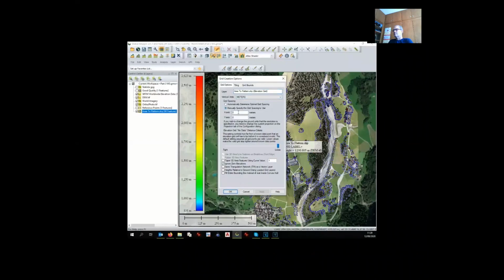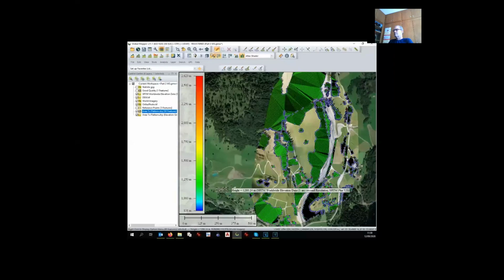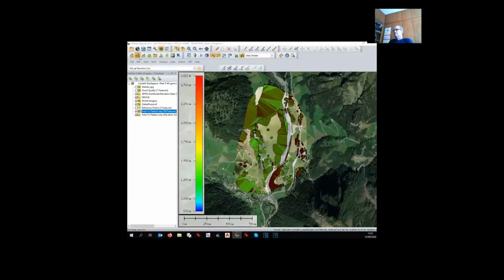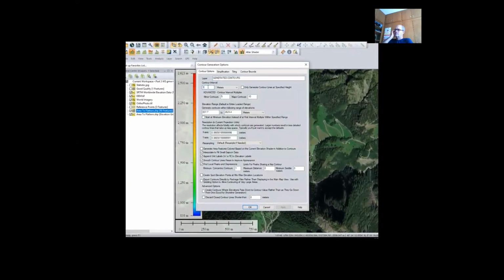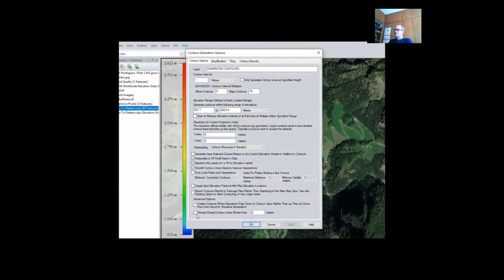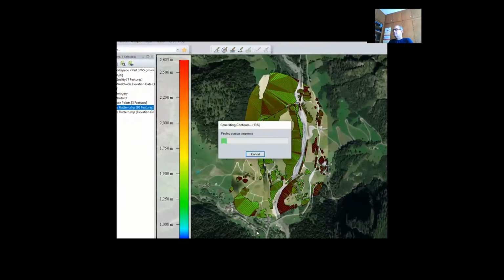manually, 1 meter resolution. Okay. If I did a good job, I should have the digital terrain model and we can verify when we do the contour line. Fine, all this area has been flattened. I uncheck. Now we can do the contour line: 1 meter equidistance, 5 meter resolution, need on it for the peak, and just what is all visible on the screen. I speed up the process.